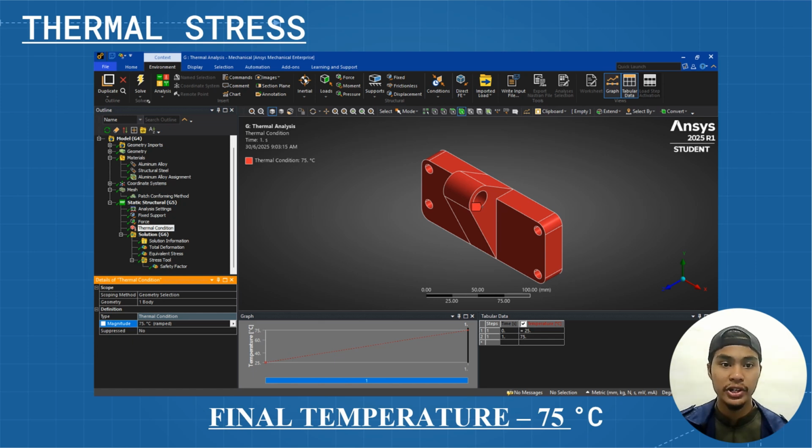to avoid material degradation. Third, steady-state versus transient analysis. 75 degrees Celsius could represent the steady-state operating condition rather than peak transient temperatures. ANSYS analysis often starts with simplified, conservative assumptions before modeling extreme cases.